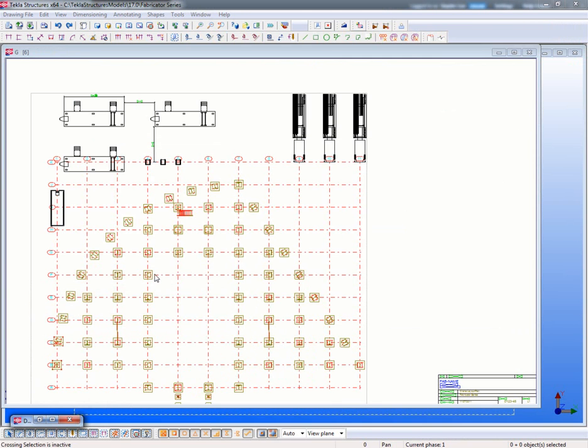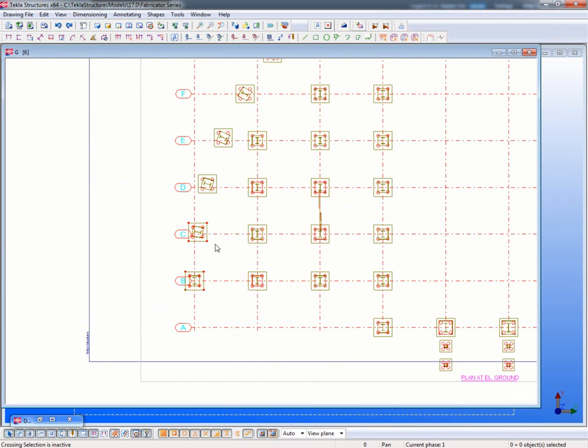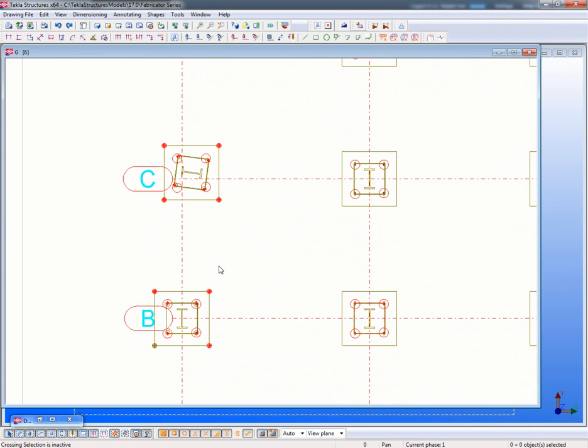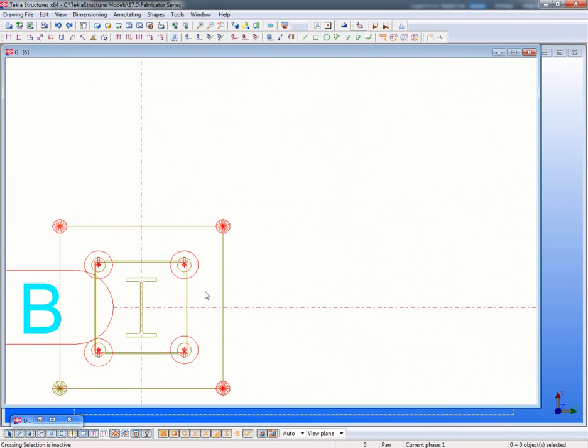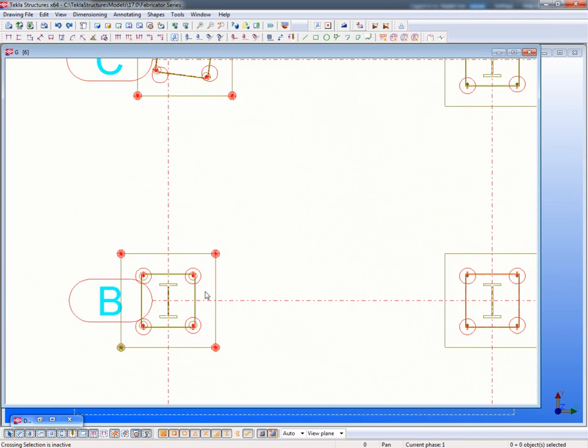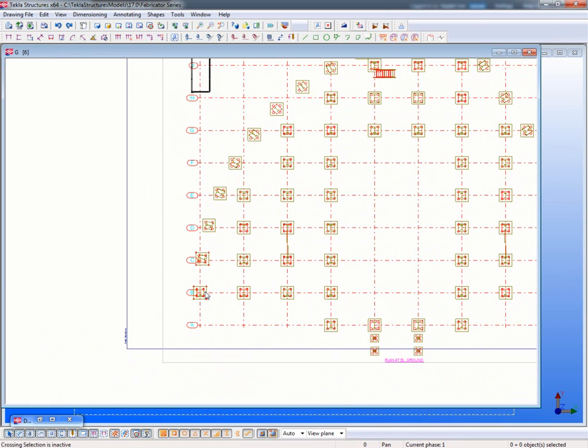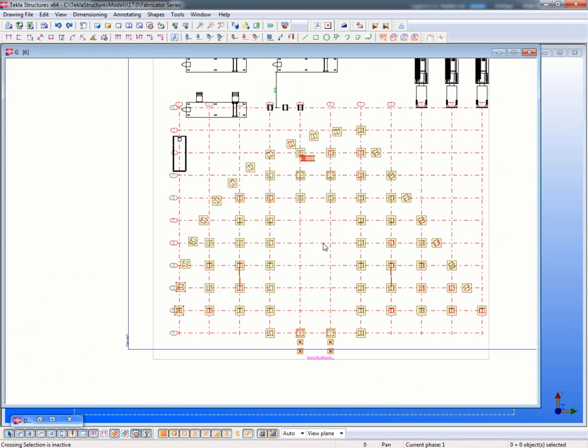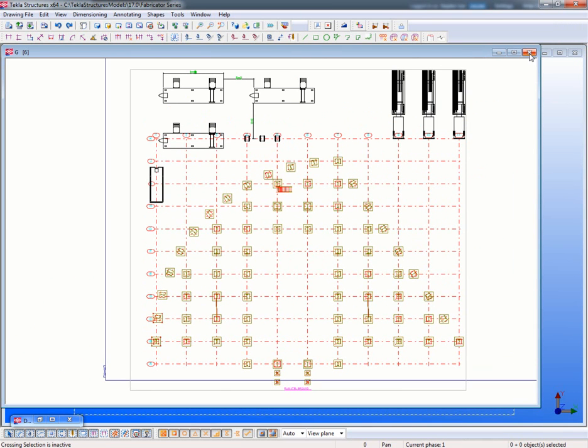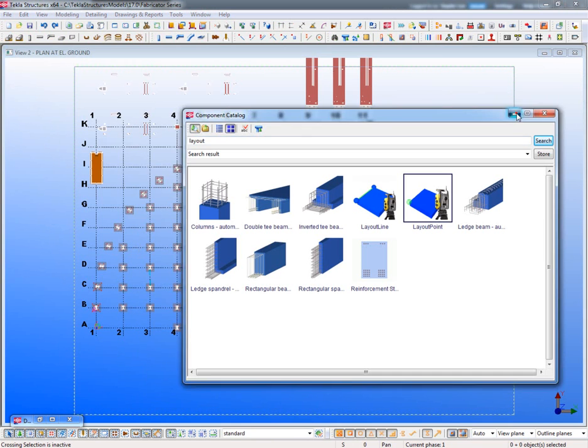So this is one way, one man with the Trimble robot and this site surveying tool can easily go out to site, stake out all these points, or gather the information from all these points, I should say, from the tops of the anchor rods, and quickly bring them back into the Tekla model and compare them. Instead of that being a two-man job taking all day, that can be one man for a couple of hours in the morning. Yeah.